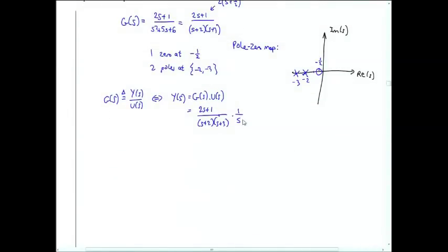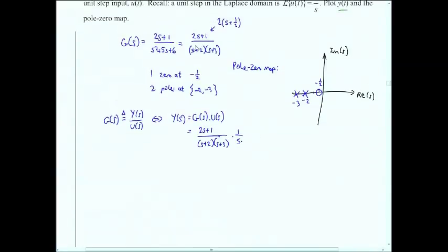And you'll get to find the time response of other input functions, like a unit ramp or a unit parabola, basically any function that we want, because we can convert that into the Laplace domain, as we've been doing. So this part may change. It's a common mistake to not include the input when trying to find the response. People just go with a transfer function and take the inverse Laplace of that.